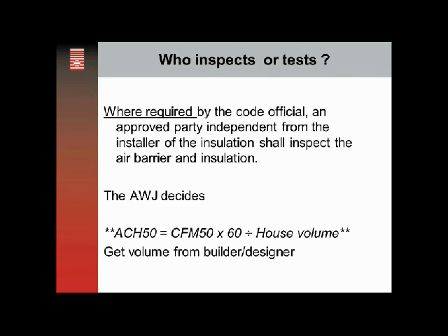provided to the testers, because the actual pass-fail is based on a precise measurement. That number, that building volume, right now, if we're sticking with air changes at 50, which we are, that number really should be submitted when the plans are submitted for review at the code office, wherever builders submit their plans. That number should be up front. Everybody should be in agreement on that number.